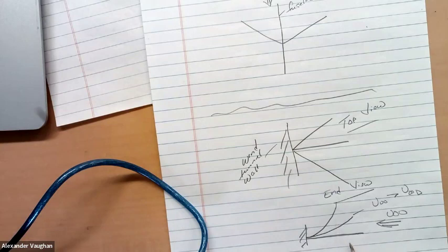will not predict what happens after divergence. Okay, it only predicts the flow velocity at which the divergence begins. If I want to predict the rest of this, I had to put in a nonlinearity in my model. And it turns out for small excursions beyond divergence flow velocity, it is principally the structural nonlinearity.